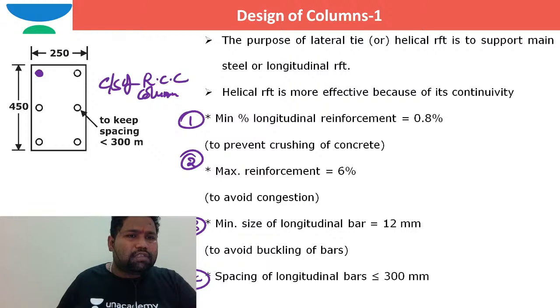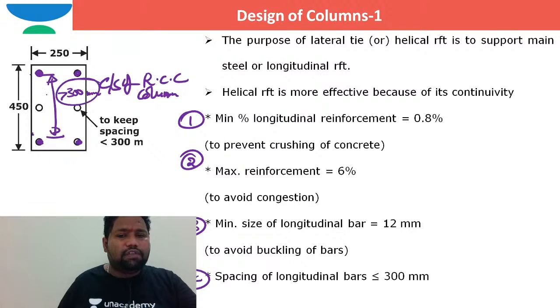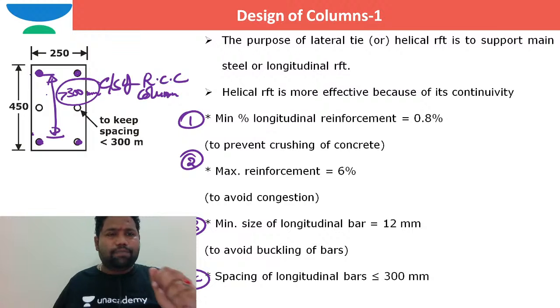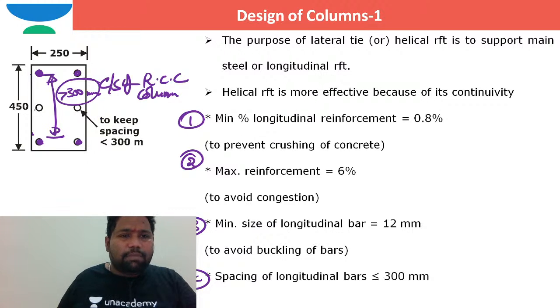Generally, people think just 4 bars are sufficient. If I had gone for 4 bars, the spacing between these 2 bars will be more than 300. In order to avoid such a thing, the spacing between the 2 longitudinal bars shall be made such that it is less than 300.